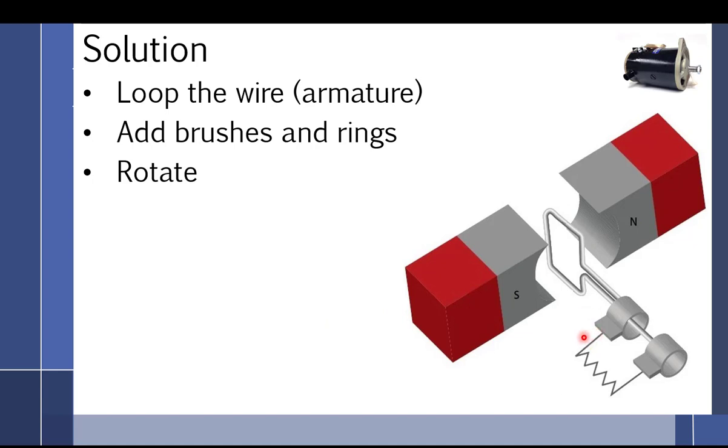All right, so you have to pay attention to some nuances here. These round tubes are called slip rings. That slip ring you can think of as welded to this bar coming out, and this slip ring right here is welded to this bar. So this one does not touch the first bar, it only touches the second one. Follow? Okay, and these are called brushes.